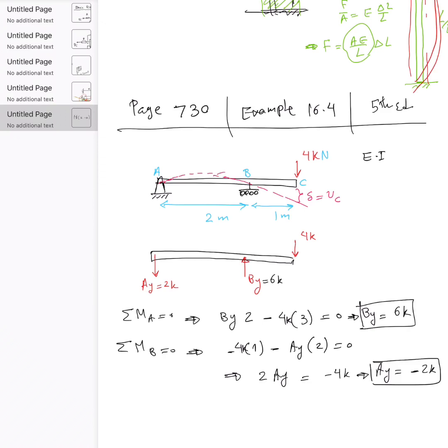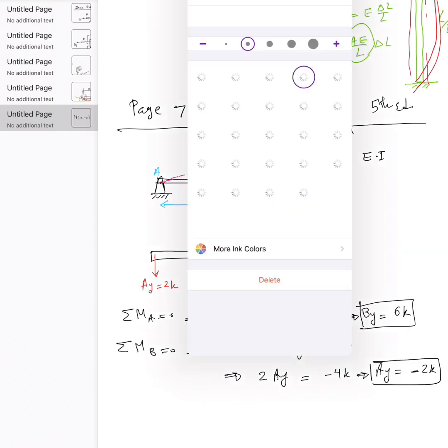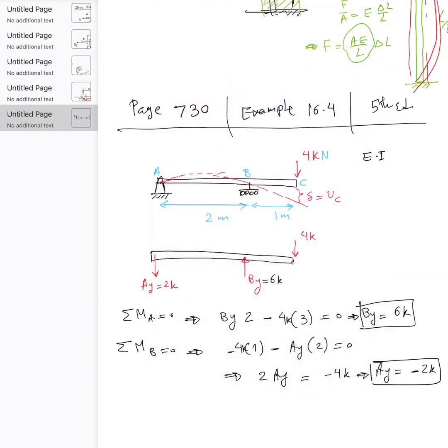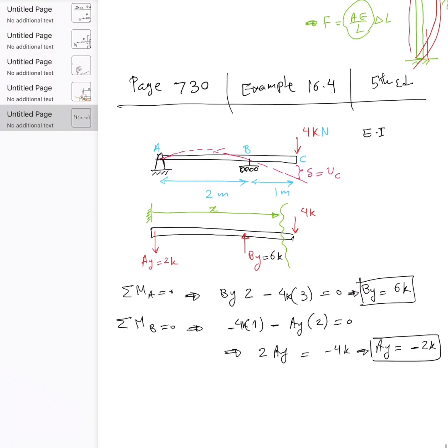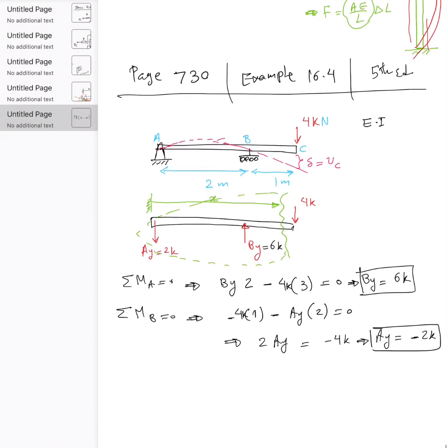Now I'm ready to go ahead and cut from left to right and apply Heaviside function. So I take my reference again from the left and I try to cut it just before the very end to include all the loads, X, and now my system is the one on the left. You don't do anything with the part on the right. That's the right system, right? So you don't do anything with the 4K. So if I draw FBD for that, I get this one.